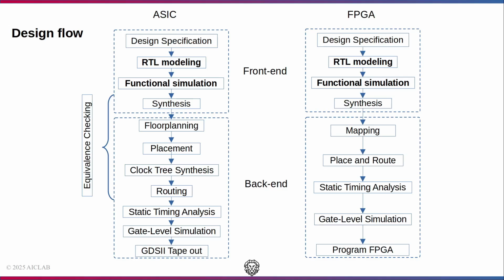Following the static timing analysis, we usually perform gate level simulation. This involves simulating the design at gate level using synthesized netlist and timing information to further verify the functionality of design after the synthesis process.